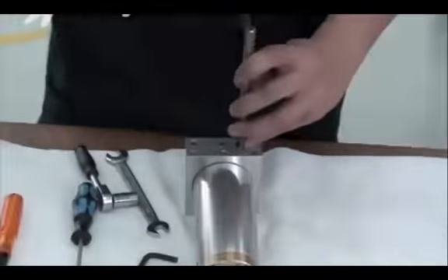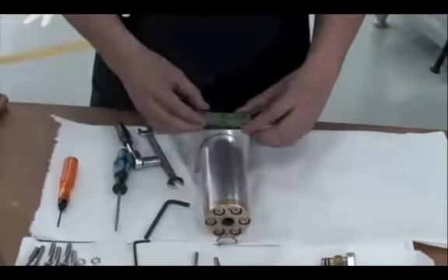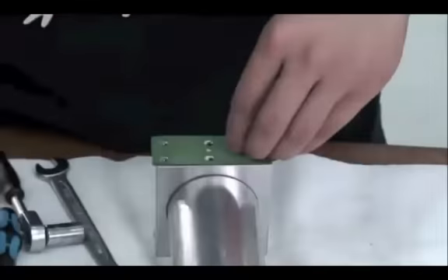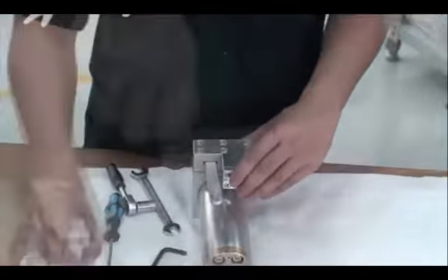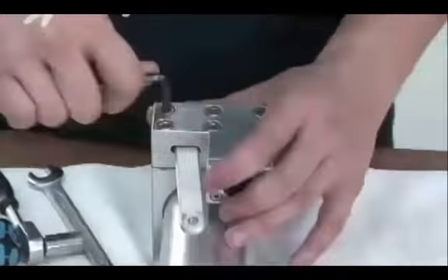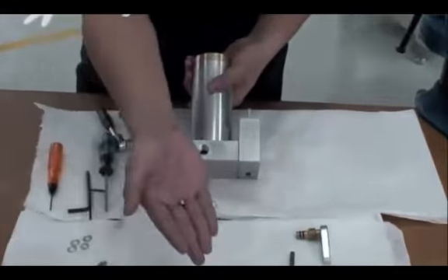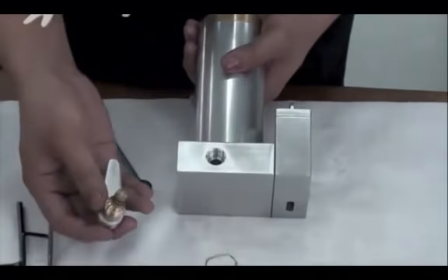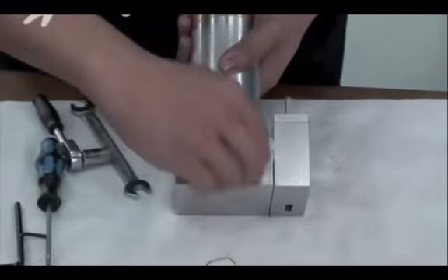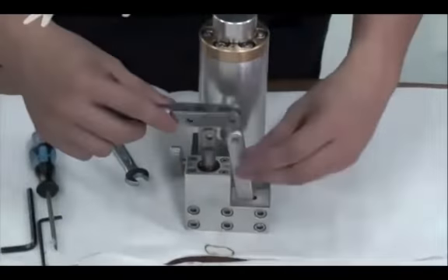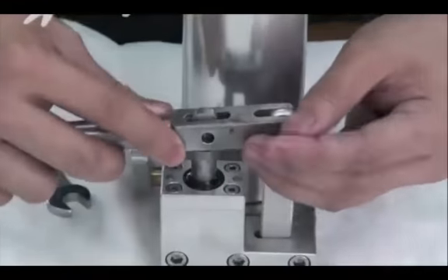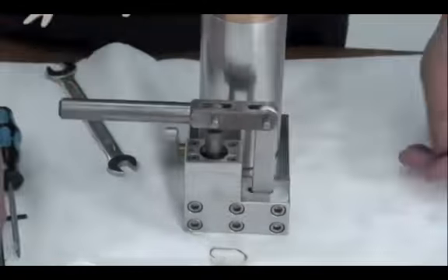This part he is assembling is the place where the small piston and the large piston come together. And so there's going to be a seal between the small piston chamber and the large piston chamber. Now he's putting in the part that allows oil to leave the large chamber and go back to the small chamber when he wants to remove the jack. And now the handle assembly is going on.